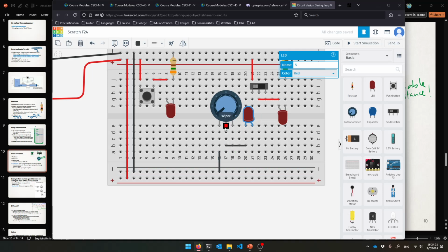So negative comes in, variably resisted, to the cathode, and then just to make sure it never blows up, we'll have our normal resistor going to positive. So you can read it backwards: positive's coming in to the anode, through the resistor to the cathode, over to the wiper, over to terminal 1, into negative. So it's connected with variable resistance.